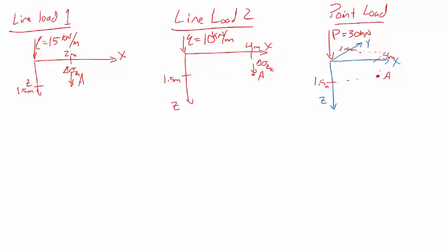And so again, based upon this information here, we have a radius. Luckily, fortunate for us, this is a 3, 4, 5 triangle. So the radius is 5, and the distance z is 1.5 meters downward. And so now we have all the coordinate system understood. Let's go ahead and calculate what that change of stress is utilizing all three of these.